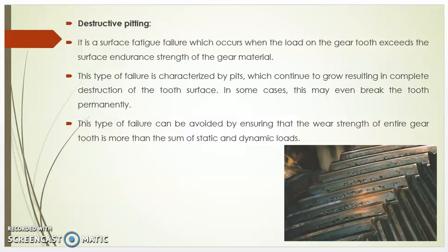Now destructive pitting. See that destructive pitting. On every tooth, more number of pits are there. Large pits are there. It is a surface fatigue failure which occurs when the load on the gear tooth exceeds the surface endurance strength of the gear material. This type of failure is characterized by pits which continue to grow, resulting in complete destruction of the tooth surface. In some cases, this may even break the tooth permanently.